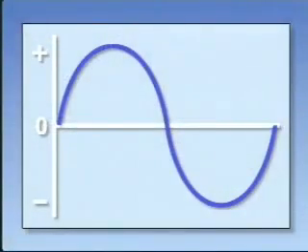This graph of a sine wave represents one cycle of alternating current. A cycle starts with the voltage at zero. To complete one cycle, the voltage increases to the maximum positive value, drops back to zero, then increases to maximum in the negative direction. Finally, the voltage returns to zero again. The rotor has completed one revolution, and both the north and south poles of the rotor's magnetic field have crossed the stator winding in the generator.